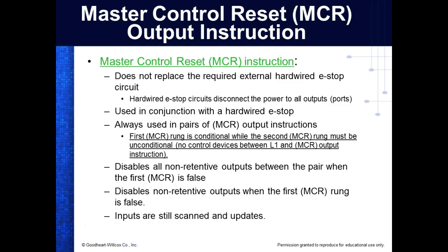So usually when we hit an e-stop, what are we gonna disable? We're gonna disable inputs or we're gonna disable outputs? Outputs can hurt people. Inputs can't, right? You understand? So normally what we do is we disable your outputs, but we got problems in that I've got a crane up there with a big magnet on it holding 2 tons of steel, and I turn that output off and it drops that steel. Right? You understand that? So this is why we have retentive contacts.